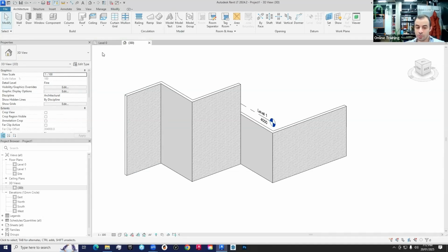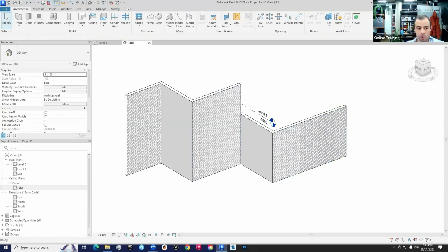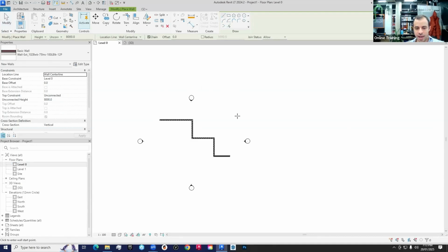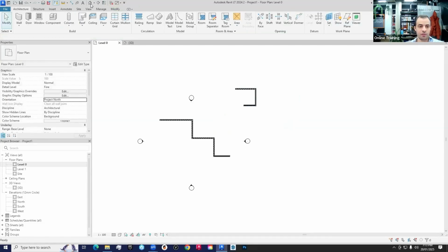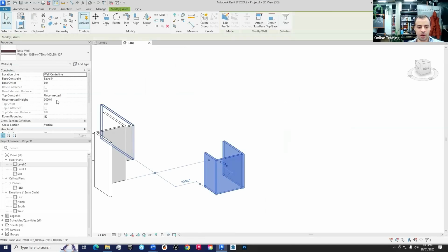Okay, so you can change the properties before drawing the element, during the modeling process, or after finishing things. You can place things and then select them and change the properties later. Or you can model a wall, and as you model it, you can change the height, for example. I'll add a couple of walls here. Okay, so now if I go to the 3D view, I can see these walls. They come already with the height that I input in the properties right away.